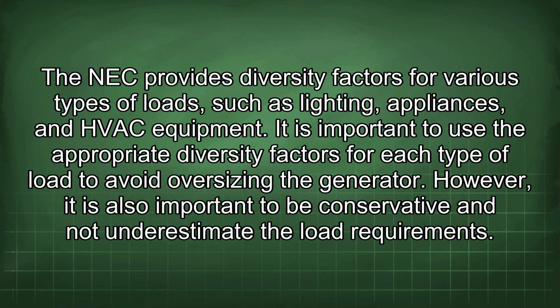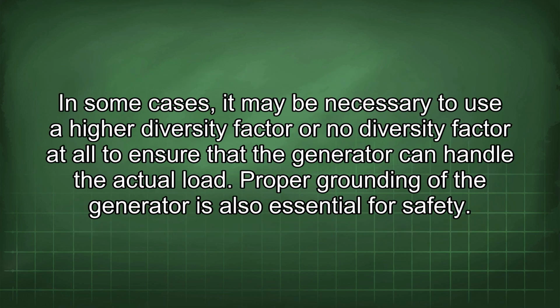The NEC provides diversity factors for various types of loads, such as lighting, appliances, and HVAC equipment. It is important to use the appropriate diversity factors for each type of load to avoid oversizing the generator. However, it is also important to be conservative and not underestimate the load requirements. In some cases, it may be necessary to use a higher diversity factor or no diversity factor at all to ensure that the generator can handle the actual load.